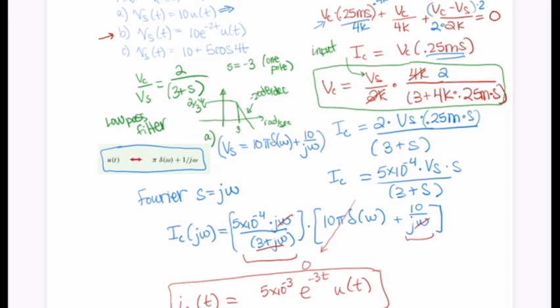So it depends on how you set up your matrix here. Here I did it in 3, so I had V1, V2, and then IT as a third. I kept IT in there as an equation, because this is to find the open voltage, but when you find ZTH, you have to put on a test source there. So then this becomes another node, so you have to sum the current IT going in there, and this current and that current. So that's where this third equation comes from.